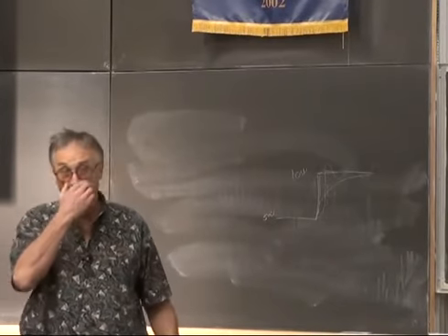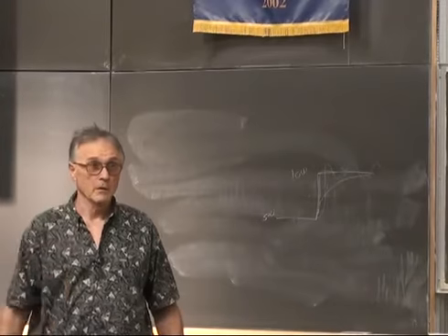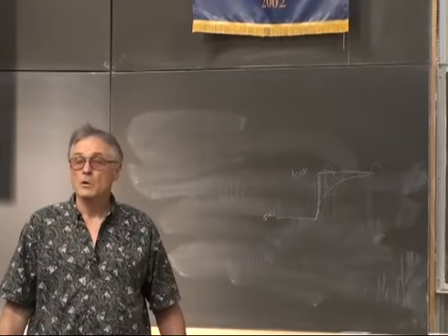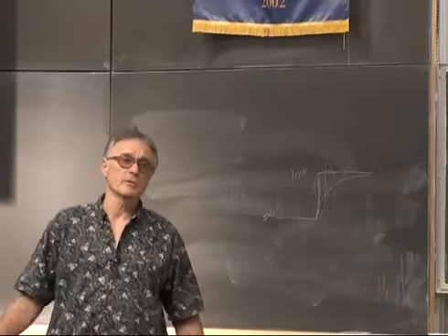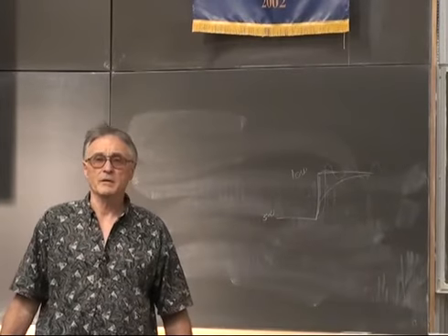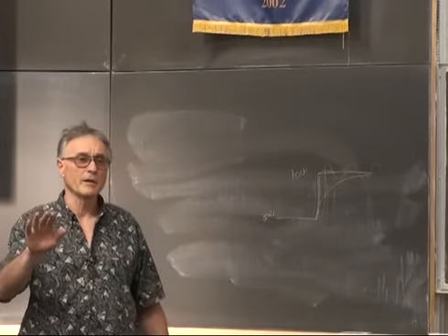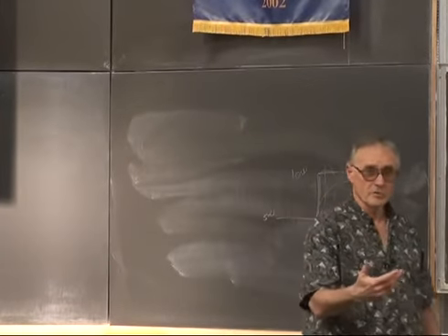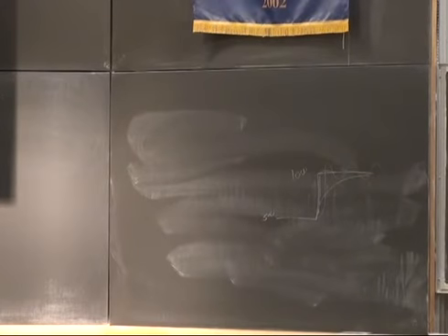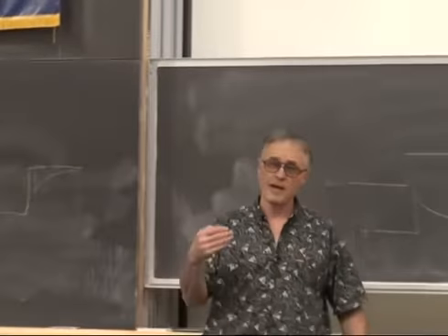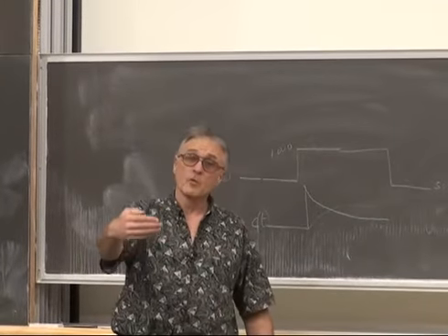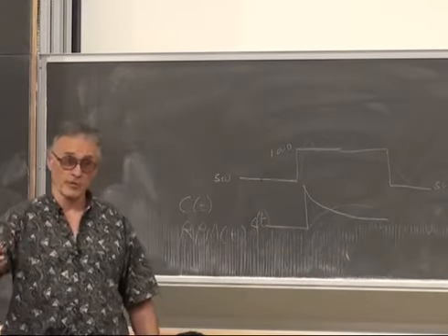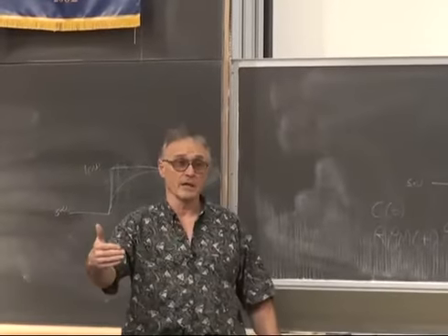So for PWM, we use like a separate timer from the input capture or the output capture timer. Sure. Yeah, use a separate timer, because you want to be able to set the period of the PWM fairly arbitrarily. And again, I would set it to 1 kilohertz or so. If you set it to 1 kilohertz, then the value of the timer prescaler will tell you the resolution of the PWM. How many counts does it take to overflow?